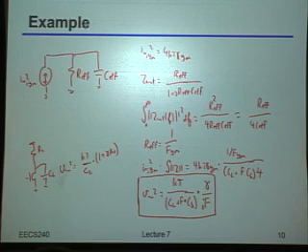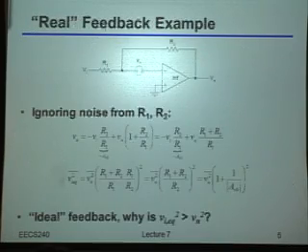Okay? Whereas over here with this open loop amplifier, obviously I added an AV in terms of the output noise, right? But when I refer that back to the input, you'd be dividing by that AV squared, right? So in other words, you are actually indeed paying some penalty from the feedback here. Now, by the way, that penalty is exactly the same as what happened back over here in this example. Because, again, notice that even though we flipped these to be capacitors instead of resistors, what we were actually doing was attenuating the signal before we actually fed it into the amplifier. Okay? Does this make sense to everybody?